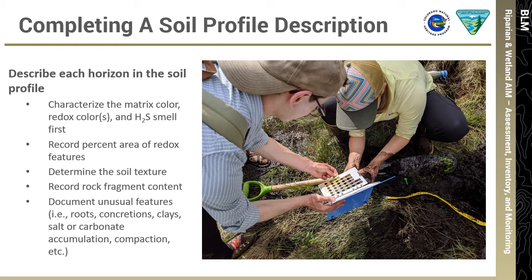For organic soils, classify by the degree of decomposition into fibric, hemic, or sapric organic soil classes. Horizon comments can be used to add additional details of the horizon. For example, to say if the texture could be a mucky mineral soil, or to provide additional information on the pattern of redox features observed.